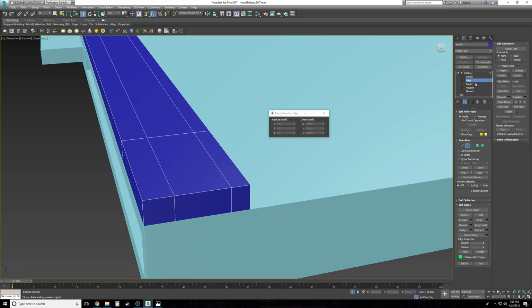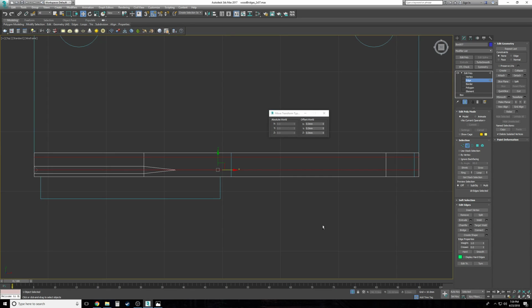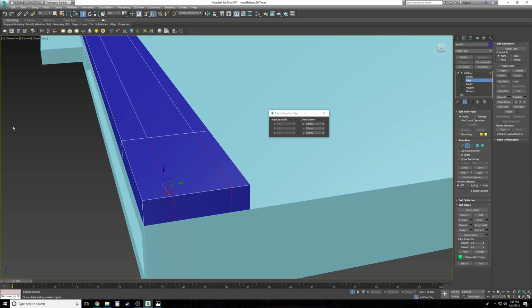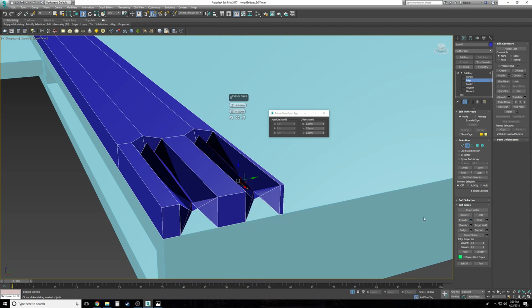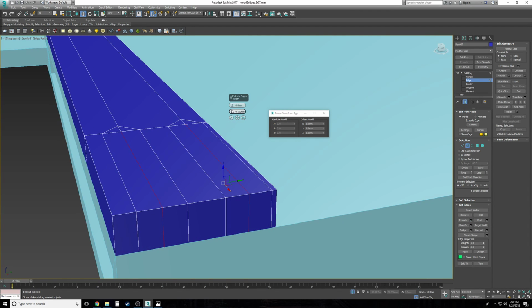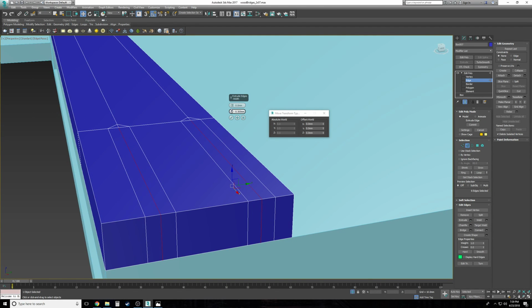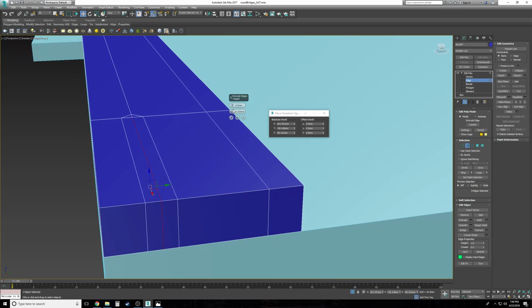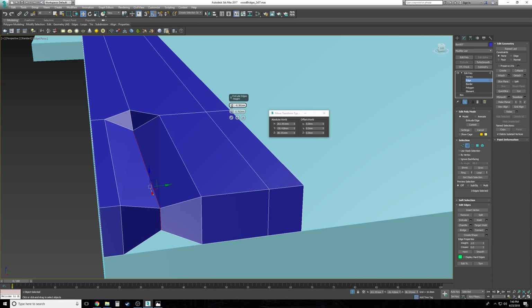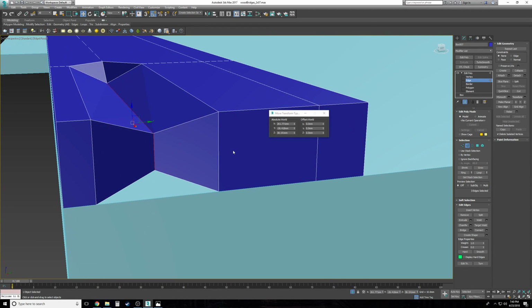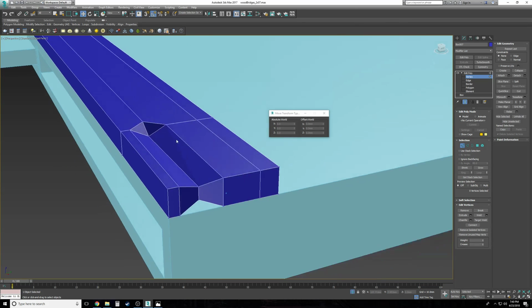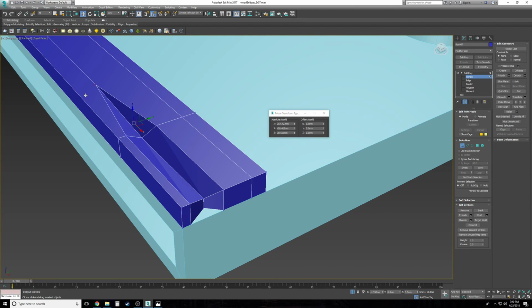And now we can go in here and go to our edge. Double click both of these, go to T, deselect everything but that little section there, and then we're going to extrude that. Well, a little bit excited there, folks. And I don't want to do both actually now, because I want these to be separate in size. So this one's going to be a little wider, but not as deep. And we'll move this piece out further.